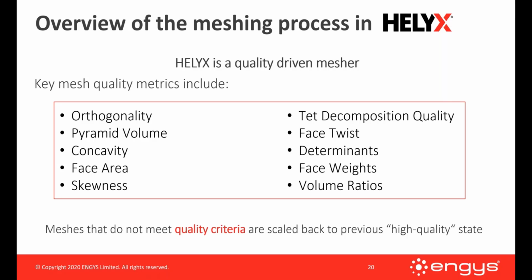Now, the dualized approach doesn't necessarily suffer by that because it will optimize the shape of these cells that might be pushed in or skewed and combines different cells. So we improve that quality through other methods than we do with the standard layer addition algorithm. Okay, so that's an overview of the quality metrics and that the mesher is a quality-driven mesher.